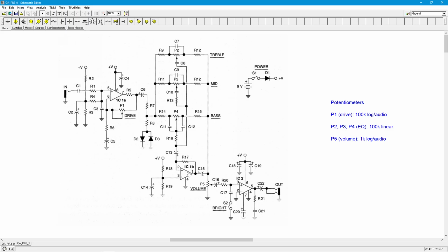First thing I want to point out, if you forgot, we're using a dual op amp here. So I'm using in the sim a TL081, but you know the dual of that would be a 082. There just isn't a model. There's really no need to have a model for an 082 or an 084, a quad, in the simulator as long as you have one of them, right? So as far as the actual chip that you buy, you could also use a 353, an LF353 would work. They're virtually identical as far as performance with an 082.